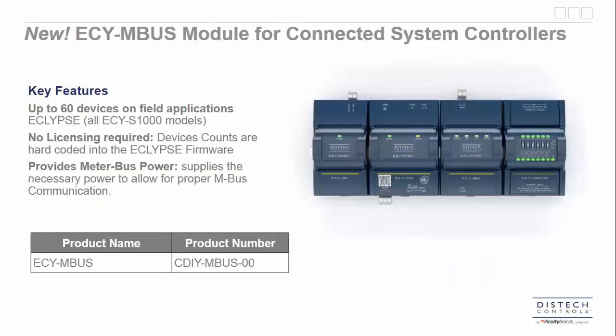All right, so the ECY-MBus module for our connected system controller. This will support up to 60 devices on the S1000. There's no licensing required. The device counts are hard-coded into the ECLYPSE firmware, so all you need to do is buy the hardware, and it provides necessary power to the meter bus.